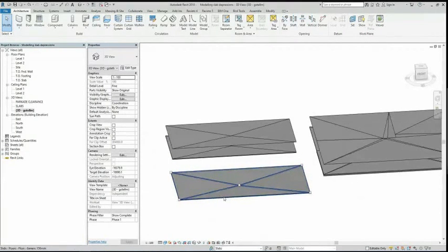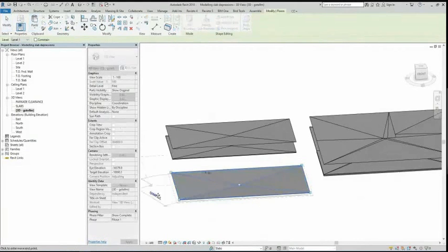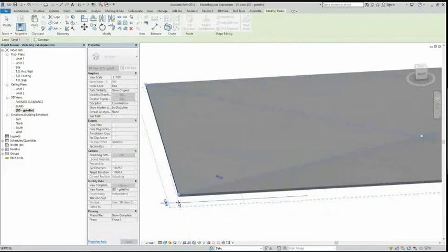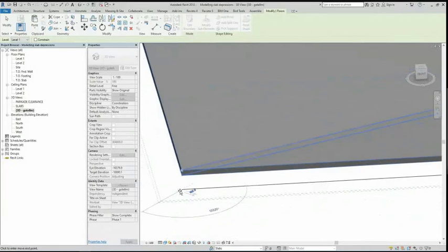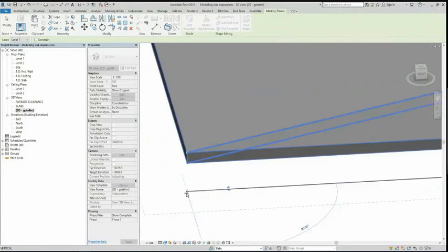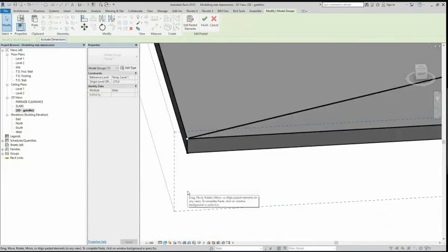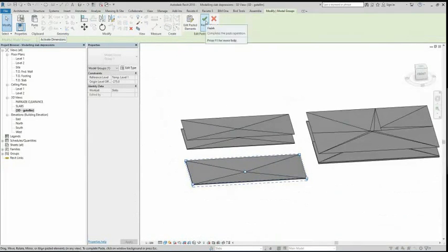So the next step is, and you can do this in 3D view or 2D view, whichever you choose, you want to select that slab element again and click copy and then paste. And when you're copying and pasting something, you gotta be really attentive to where you align it. Otherwise, your slab elements might not align, not vertically, but horizontally in the X and Y layout. So in Revit, you just want to make sure you're at the edge of this line and that the digits on it say 0, 0, so that there's no offset whatsoever. And click enter, or just click on that, and you have the second floor slab pasted.